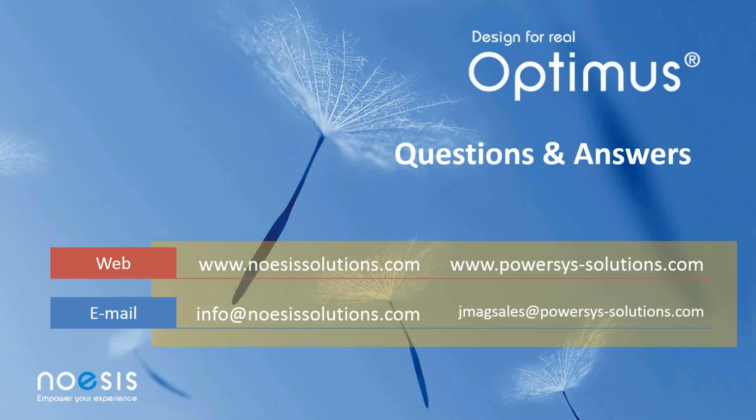In addition, we've gone above and beyond with some of our RSMs where we calculate what's known as the leave one out error. Basically, we'll take the response surface and just remove one of the known points, calculate the difference between what the surface would calculate that value to be and what that value actually was. We'll do that same process on every single point, summate that data and return that, and that's known, of course, as the leave one out error. So there are a number of different ways that we can determine that quality, and all of that information is fed back to the user.